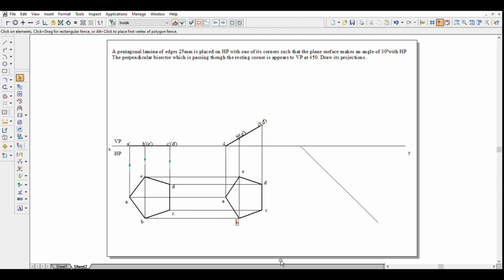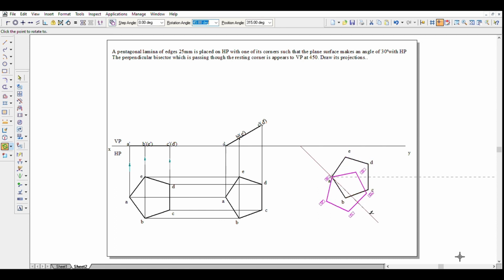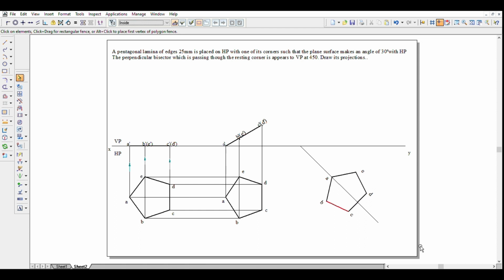Now we have to place this given figure on the point such that the point A is on the axis of the line that we have drawn. So we'll use the select tool and select the diagram completely along with the annotations. We'll move a copy and select the point to which we want to move. We can place it a little below. And now we can use the rotate tool to select the two points for rotation. Initial point, we'll use the midpoint as the final. And now we can place it on the axis. Now we have the pentagon given view.